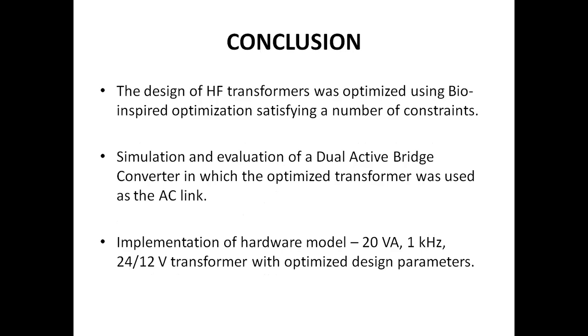Concluding, the design of high-frequency transformers was optimized implementing a bio-inspired optimization algorithm, that is, the genetic algorithm, taking into consideration physical, thermal, and electrical constraints. A working dual-active bridge converter was designed and simulated using the previously determined high-frequency isolation transformer specifications. The converter was found to exhibit low power loss and good output regulation in comparison to non-optimized transformers. A hardware model of a dual-active bridge converter was implemented with the approximation of an inductor instead of a transformer for the rating of 20 VA, 1 kHz, and 24 volts 12 volts.